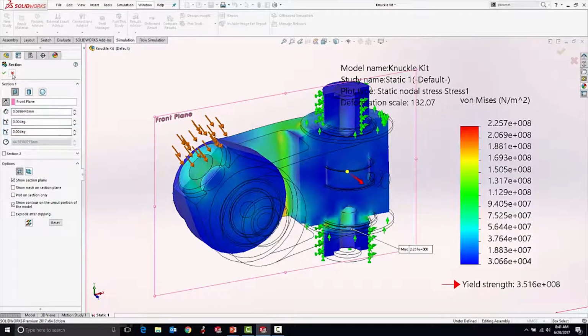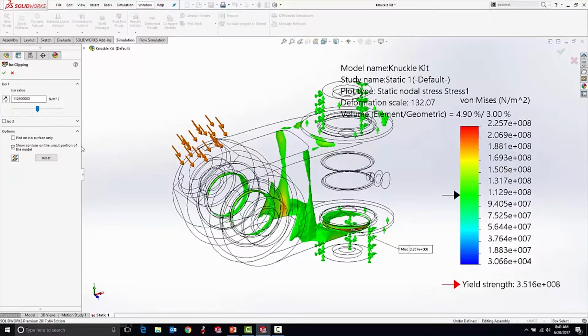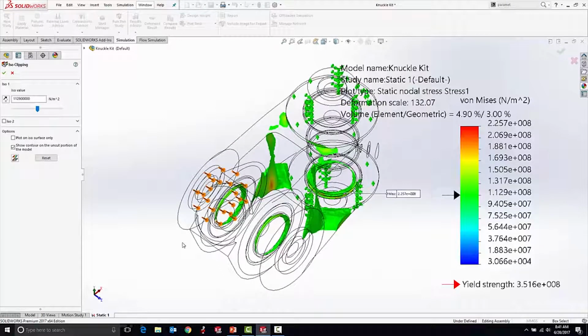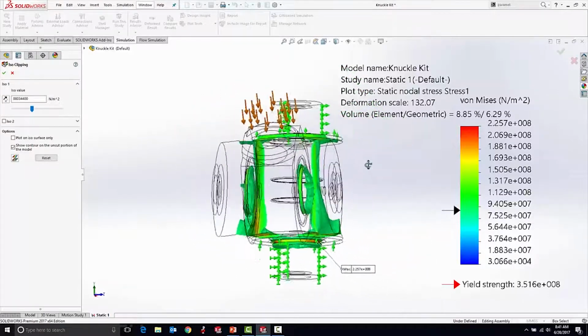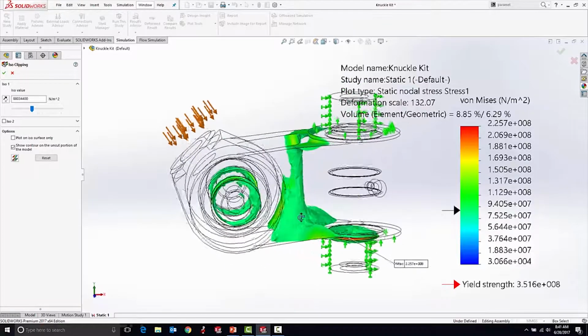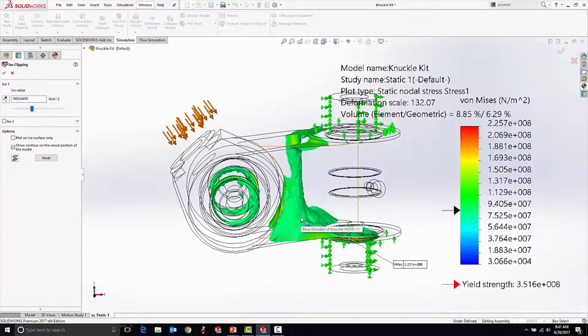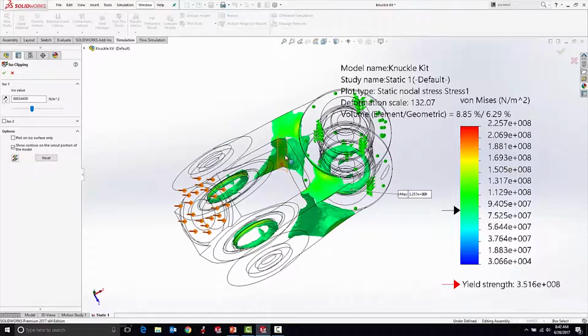Now that's really hugely useful a lot of the time, but if I want to really hone in on high stress areas, what I would use is the ISO clipping. What the ISO clipping does, instead of showing me stresses that are on one side or the other of a plane, is hide or show stresses that are above or below a particular value. So I can look through my part and see which pieces of material are very close to failure, and also I might want to see which areas of the part are not doing a whole lot of work, where I could maybe stand to thin out the material a little bit, right? Maybe these arms could be a little bit skinnier for what they're doing, since really it's just the material at the corners that's doing most of the work. This could inform me to either add or subtract material to make a more efficient, better design.